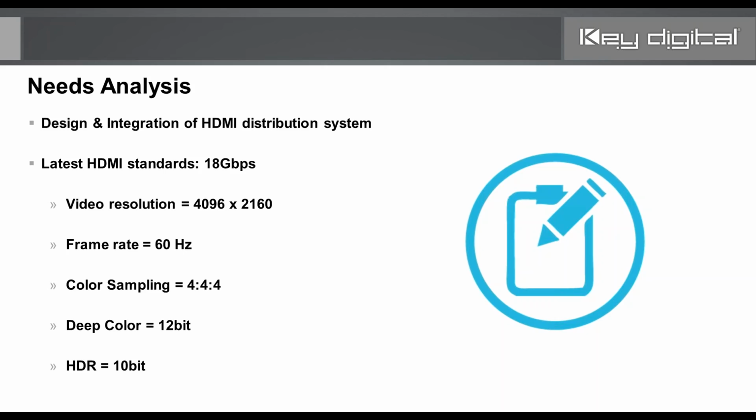improvement to picture quality. In order for your HDR-compatible source device to output that signal, it must receive a handshake for 12-bit deep color as well. So all of these parameters, resolution, frame rate, color sampling, deep color, and HDR, if all those things are maxed out, you could end up with an 18 gigabit per second signal. And that creates a problem